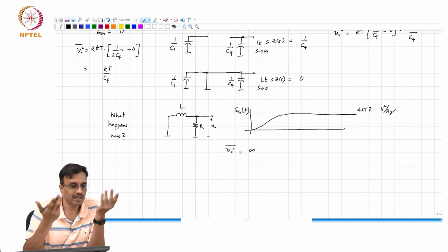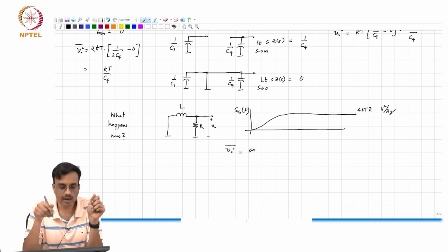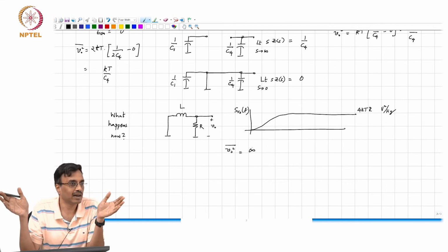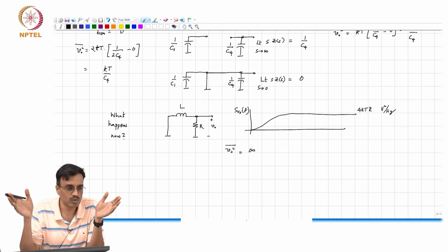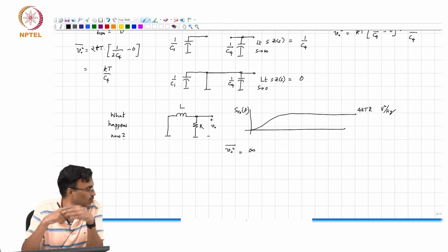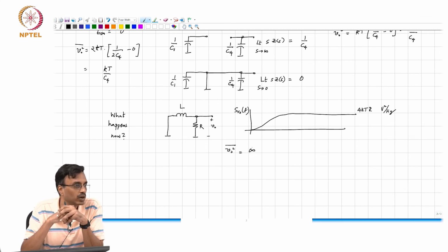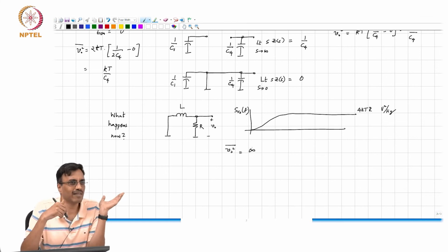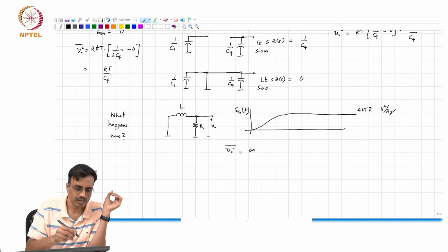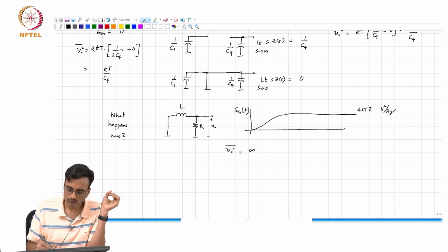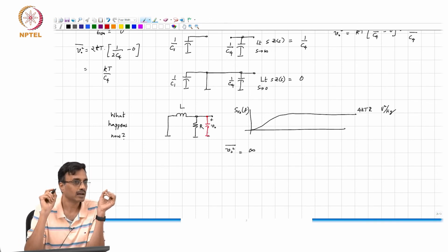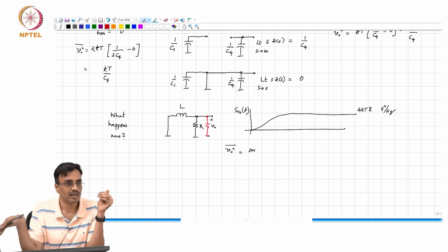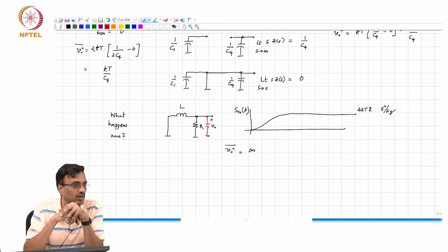And again this is telling us that, oh well, if I simply put an inductor or resistor like that, I will get infinite mean square voltage, which evidently sounds too good to be true. So in reality you will never have a network like this, because, oh well, every node is associated with parasitic capacitance, correct, and eventually the spectrum must fall off.